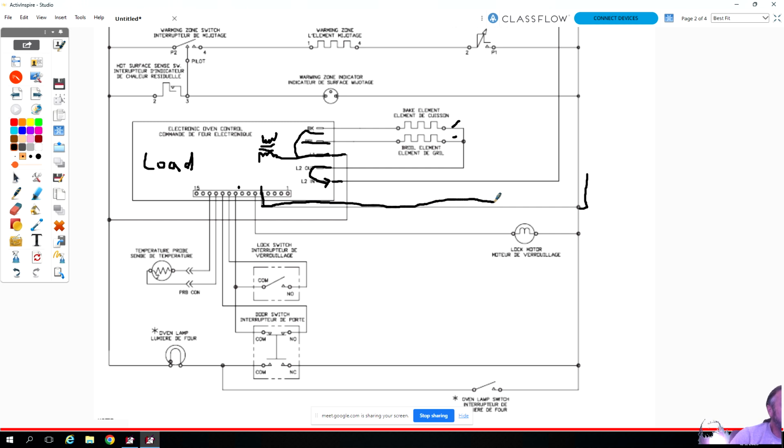That's our input voltage. So what do we do with it now? If I see that that's my input voltage and my board didn't work, what's your next step? We looked at the diagram, we saw that this is where power's coming in. What do we do next? I would check for a broken wire on neutral if I'm getting live. Okay, well, on L1, you'd make the test first, right? You'd go right to the board and you would put your meter leads.